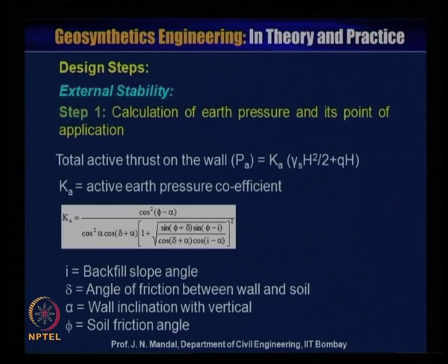Now how will you design this? I will show you that design step, and then we will solve one example. Now in design step, you have to go for external stability. So step 1, calculation of the earth pressure and its point of application.